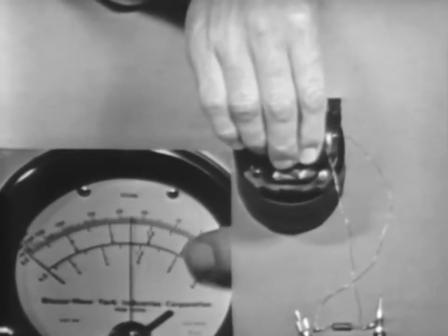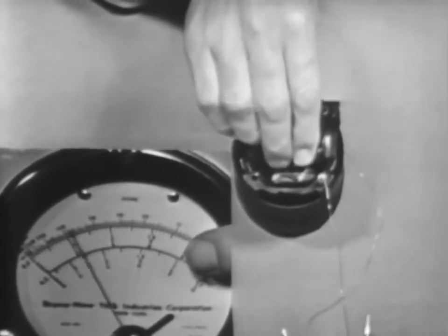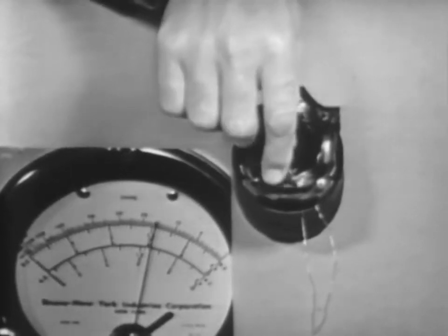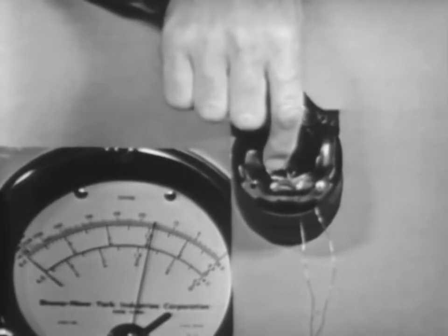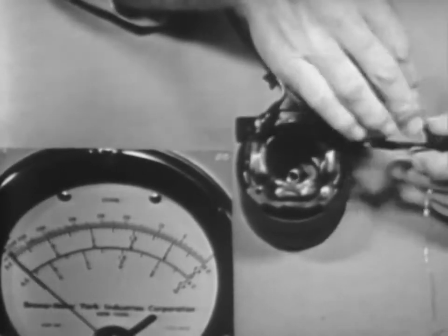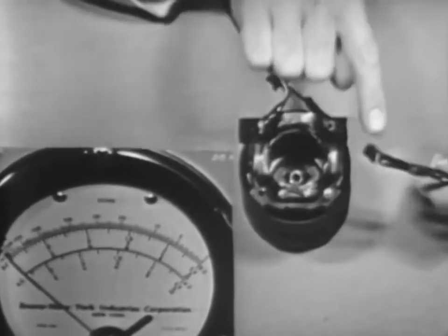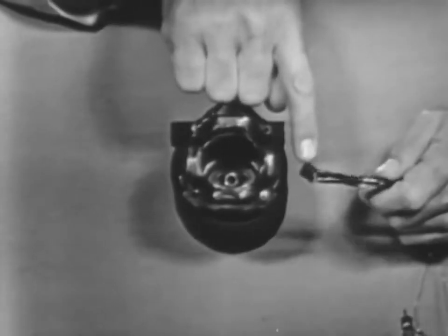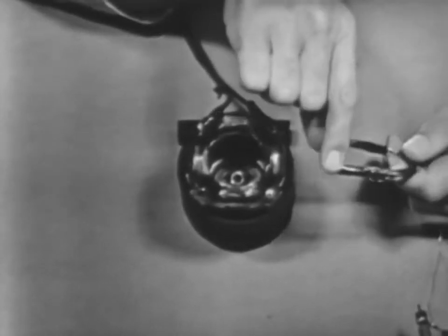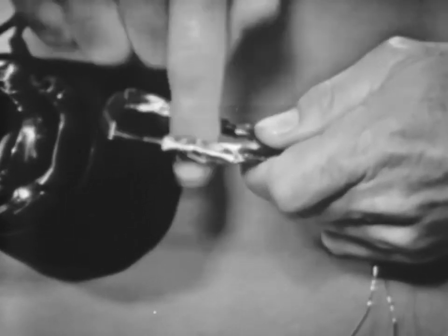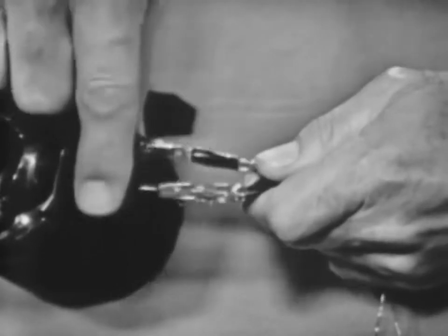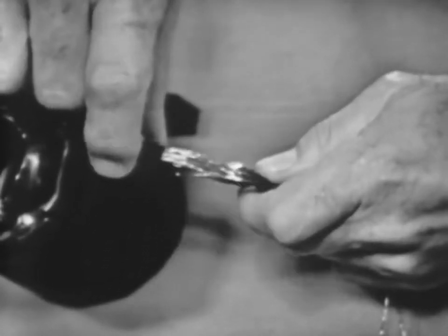That's the induced voltage from this loop. And you can see as I take the loop out, it goes away, put the loop back in. I've got to get the loop all the way down in there. There you go. Now we have the rotating magnetic field inducing a voltage into the loop, which we're reading on the PSM6. The important thing to realize here is that once we get current flowing in this loop of wire, we have a magnetic field established about the loop. This means that we'll exhibit a north pole on one side and a south pole on the other. In other words, we have magnetized the loop, made it an electromagnet.